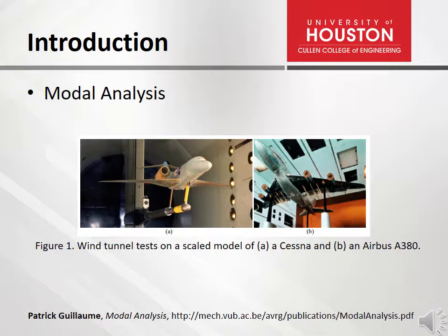Wings of airplanes can be subjected to a similar flutter phenomenon during flight. Before an airplane is released, flight flutter tests have to be performed to detect possible onset of flutter. The classical flight flutter testing approach is to expand the flight envelope of an airplane by performing a vibration test at constant flight conditions, curve fit the data to estimate the resonance frequencies and damping ratios, and then plot these frequencies and damping estimates against flight speed or Mach number.